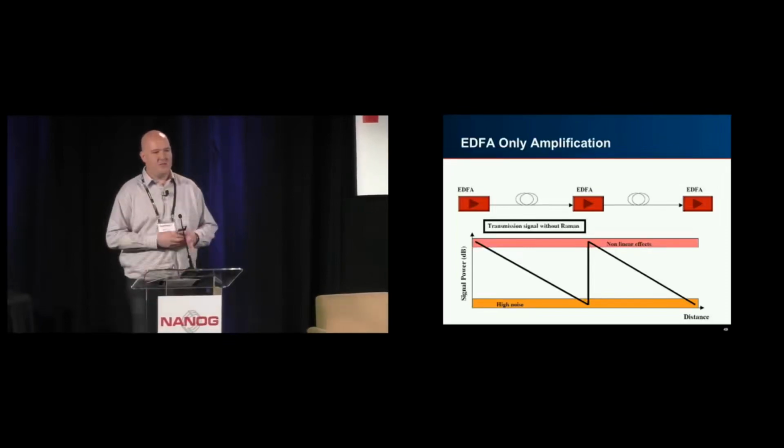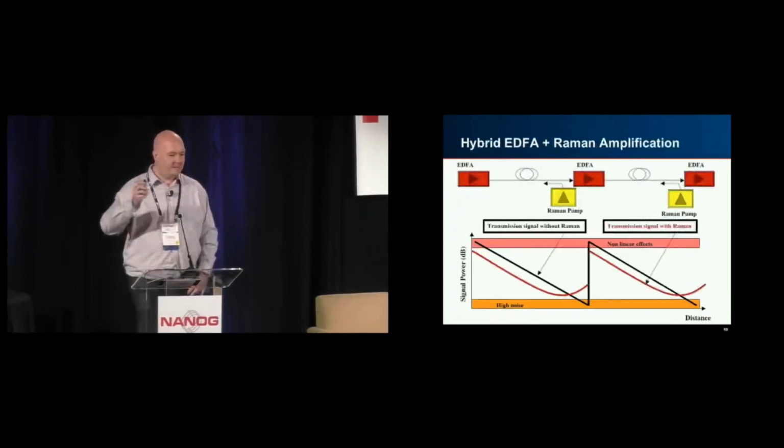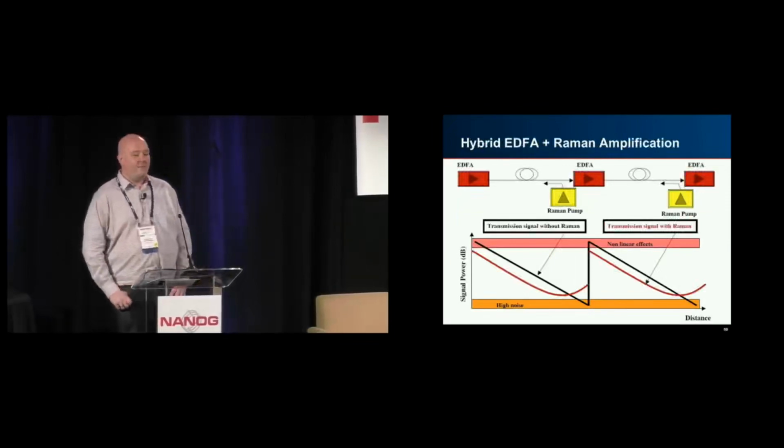So this is showing an EDFA amplification. You see the penalties that you're going to pay here. You had to launch at a very high power to get it out, and you had to receive at a very low power before you amplified it, so you've lost a lot of OSNR in the process. In a hybrid EDFA Raman amplification, what happens is you add a Raman pump and you send it the opposite direction.